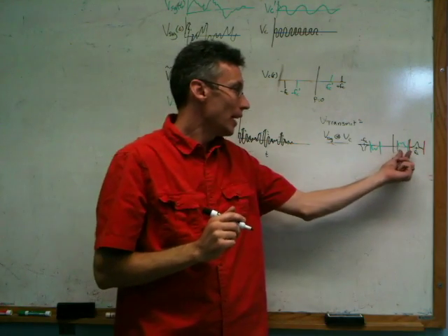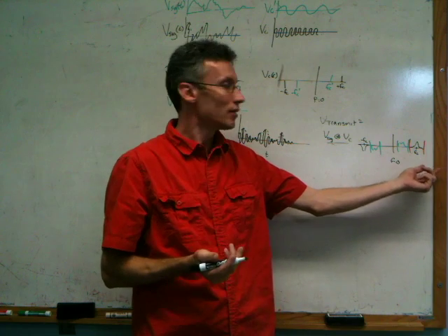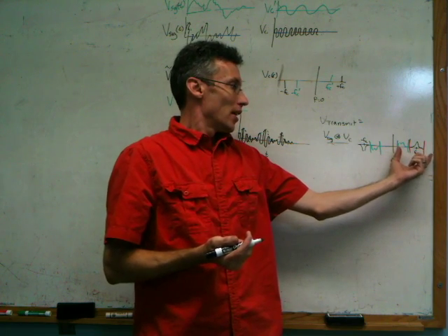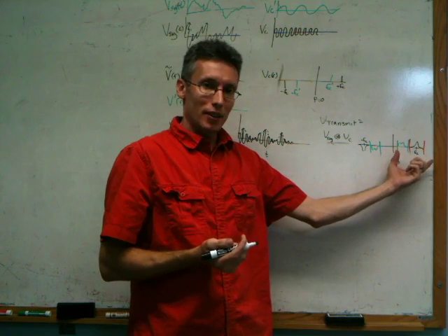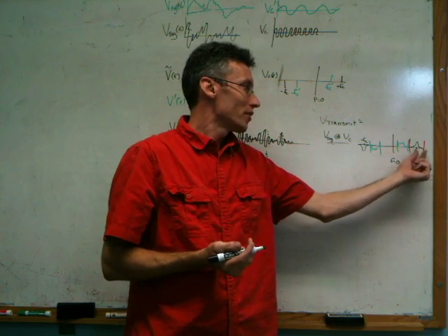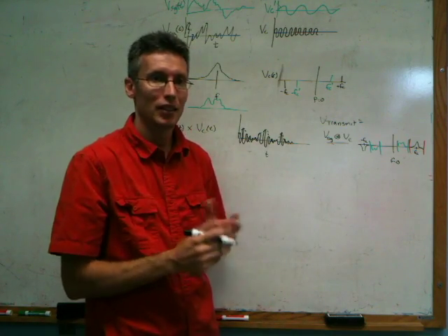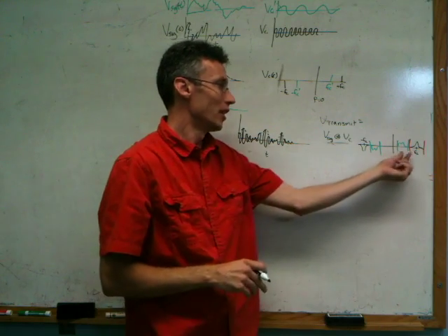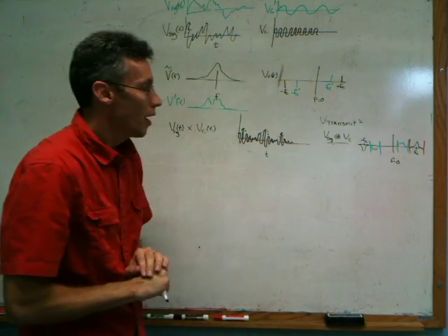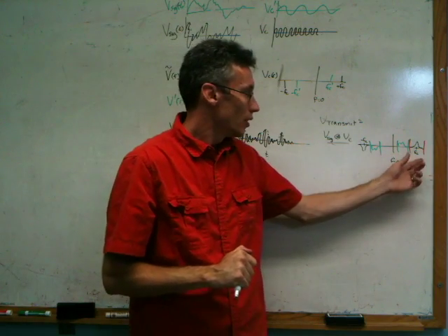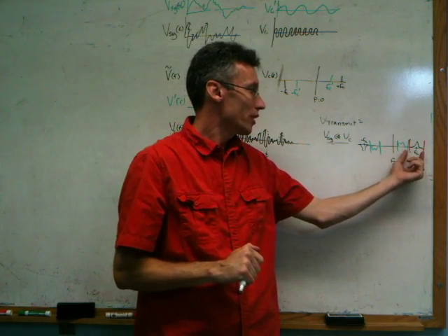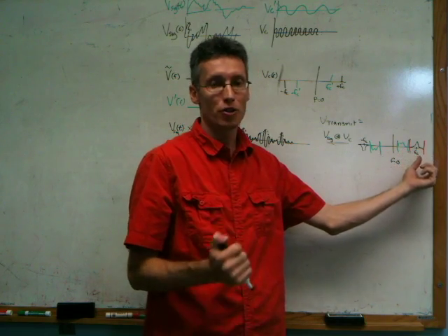And by doing it this way, I can encode many different channels on this transmitted signal, and the information can be separated and later recovered independently of what's in the other channels. It is also useful to do this modulation because I can choose the frequency region at which the information is transmitted.